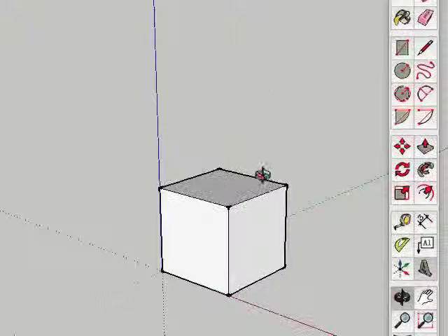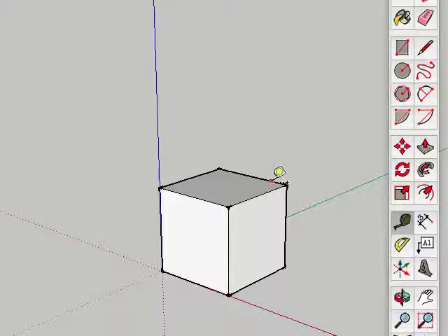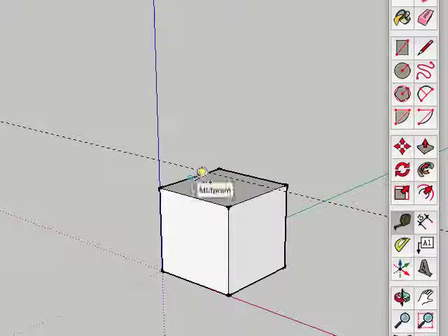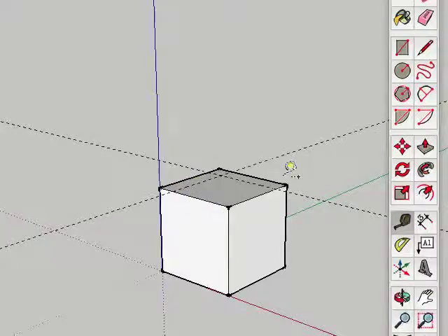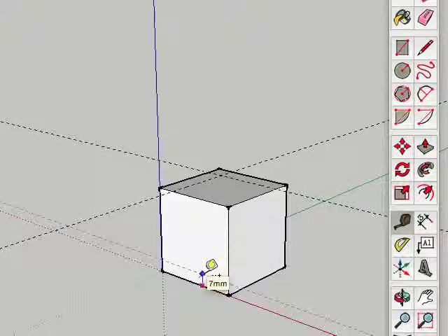So if I go back to SketchUp, I grab my tape measure. Now it's good if you get right on the line, not on the midpoint or on the corner. I wanted a line in at 10, so don't pick the midpoint there, it doesn't seem to work properly. Don't pick a corner, try and get on an edge. I come 10. So as you can see already, that's going to be my L shape there. And I'm going to move that up. Again 10.